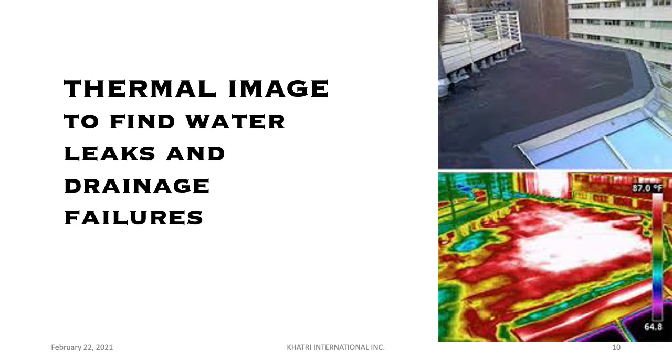And then, of course, the use of thermal imaging. Thermal imaging is very powerful. This is just a sample shot. We use this in our office. We have the instrumentation to look for variations in temperature, which will tell us where possible water has collected, where there may be a leak occurring. It's also used to determine heat loss for purposes of insulation, but it's a very powerful tool to search for leaks and drainage failures. And these are non-destructive methods.